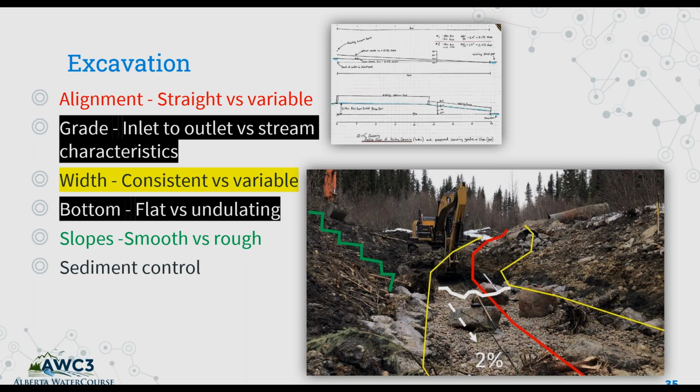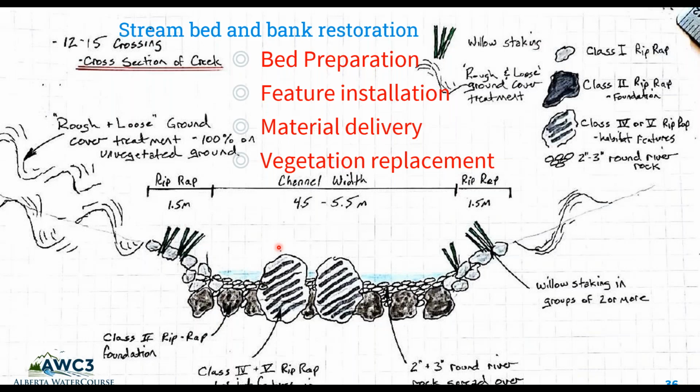Understanding your restoration plan. So now that your creek is excavated, you'll want to understand your restoration plan: what grade you have selected, the width, what is placed first. Can you do this as you excavate? You want to think about delivering your materials, revegetation and willow staking your slopes, and installing erosion bars. You may want to make sure you're installing erosion bars upstream of your creek while you're excavating your creeks.